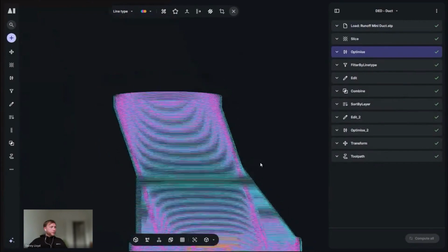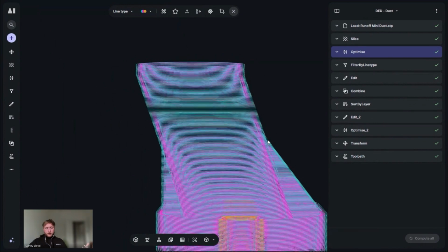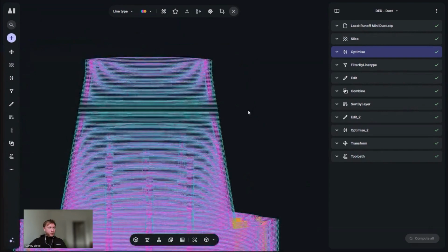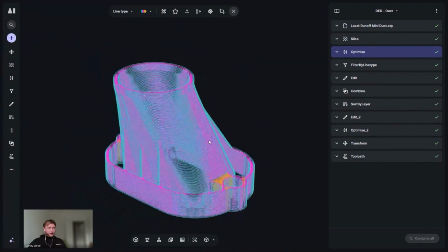We can also see that this part has an overhang. That might be an achievable overhang, in this case it's powder laser DED. But regardless, we're going to see a reduction in quality here because the laser isn't as concentrated, because you've got some step over, because the powder's going to miss a bit. What would be ideal is if our tool was oriented normal to that angle here. But you don't want to angle it everywhere the same, because here we might want it here, and here we want it here. So how do we do that?